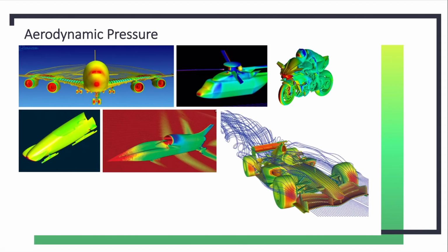And lastly, we've got an example of a Formula 1 car. Again, we see quite large pressure regions on the nose and on the wheels, a little bit on the helmet, and again on the air intake up there. You'll also see quite a lot on the front wing, and also on the rear wing. That's for a slightly different reason, because you actually need that pressure to generate lift or downforce.